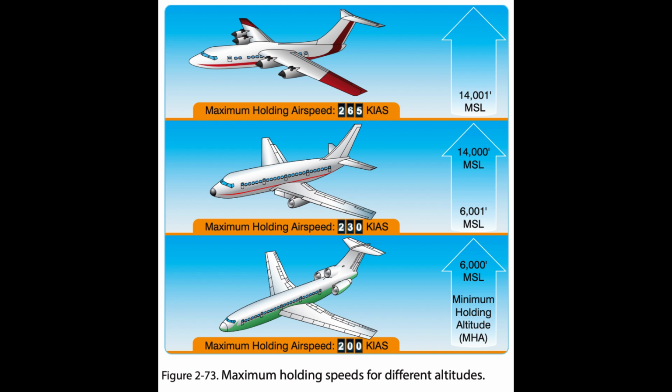Generally, TOC is used in aircraft with an FMS, and represents the point at which cruise altitude is first reached. TOC is calculated based on current altitude, climb speed, and cruise altitude. The pilot may elect to delete the additional waypoint recording requirement if the flight is so short that the record will not assist in the management of the flight.